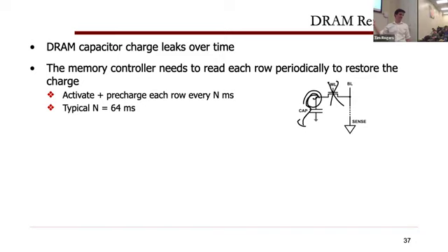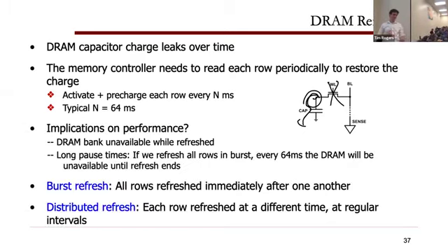There's a huge security hole with the 64 millisecond refresh as well, because if you know it's going to take exactly 64 milliseconds, then you can hide something in there. So DRAM manufacturers like Micron actually have a classified amount of time, somewhere around 30 or 40 milliseconds. They don't tell you precisely how frequently they refresh. Physically, it's about 64 milliseconds, but they may mess with it from an adversarial perspective, because 64 is just the limit. You can go lower if you want to.